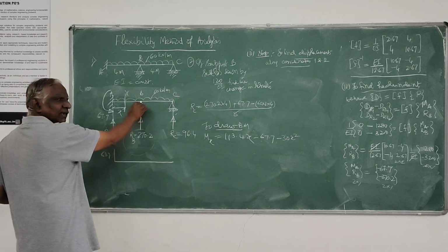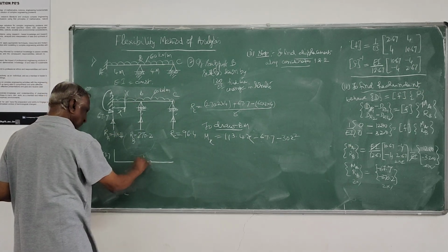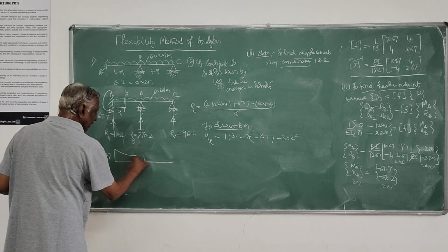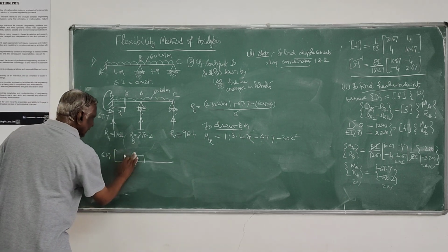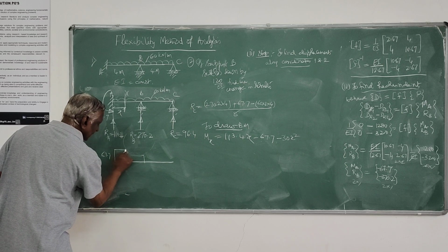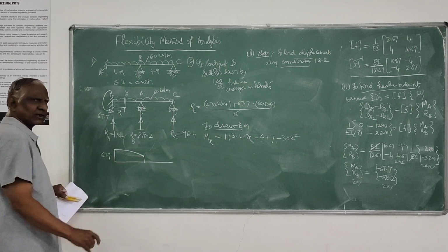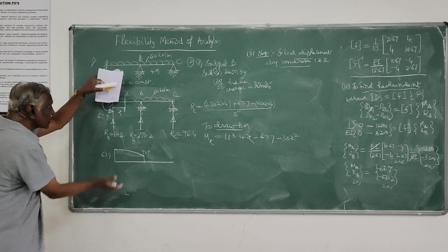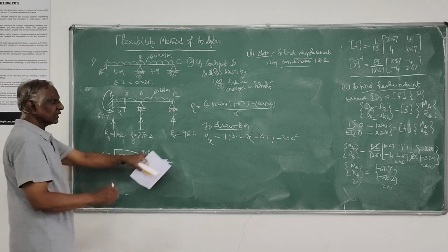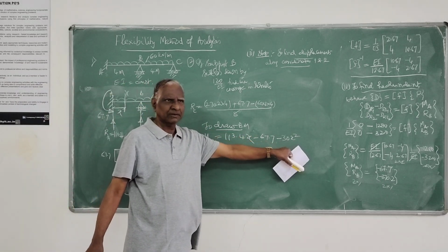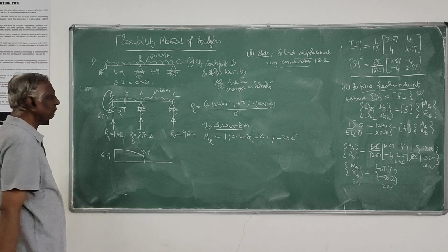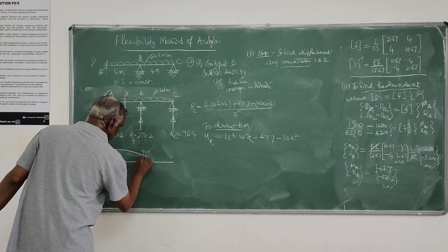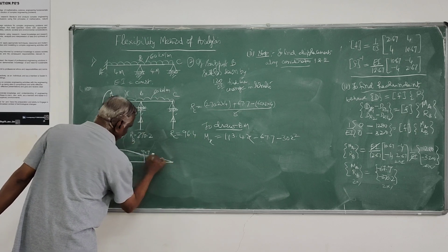Then you can find out what the bending moment is here. Whatever the bending moment is, you get that straight away. So you can plot it by parabolas, a second degree curve, minus 94.1. Whatever it comes to at this point, and 4.4, this is the diagram. You need not superimpose the free moment diagram because I have already taken that here. So you will get the net bending moment diagram straight away. So probably you may get a bending moment diagram in that fashion.